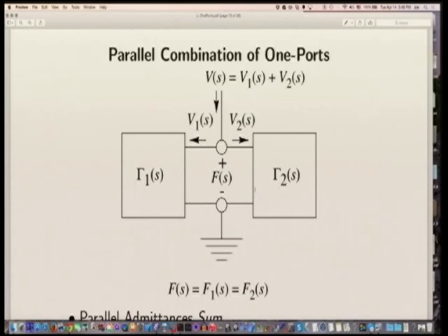So you will want to shrink the circuit down to where it's true, and that's why VLSI works. You can have a nanosecond clock cycle if things are just microns away. It works out. But transmission line effects are kind of the next level, and we're going to get there. But the way we'll get there is, when we're done with lumped modeling, we'll go to traveling waves and acoustic tubes. And that'll give us things like the speech model that I demonstrated on the first day that was done at Bell Labs.